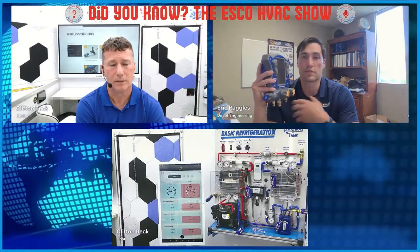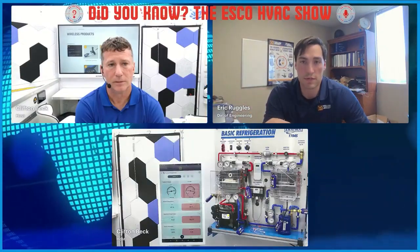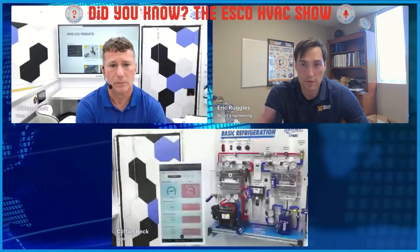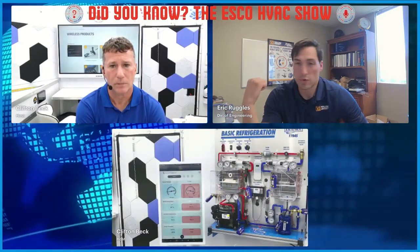If you want to charge the system, you can charge through your manifold, or just connect the manifold to the system if you need to. Certainly, you can use the temperature clamps, or you can use the ones that are wired to the back of it. It connects to the dew point sensors, so you have the psychrometer section as well, right on the Titan Max. So it's useful as well. It's all connected. I can take pressures and temperatures directly from that into the app, rather than having to connect to 4 different sensors.